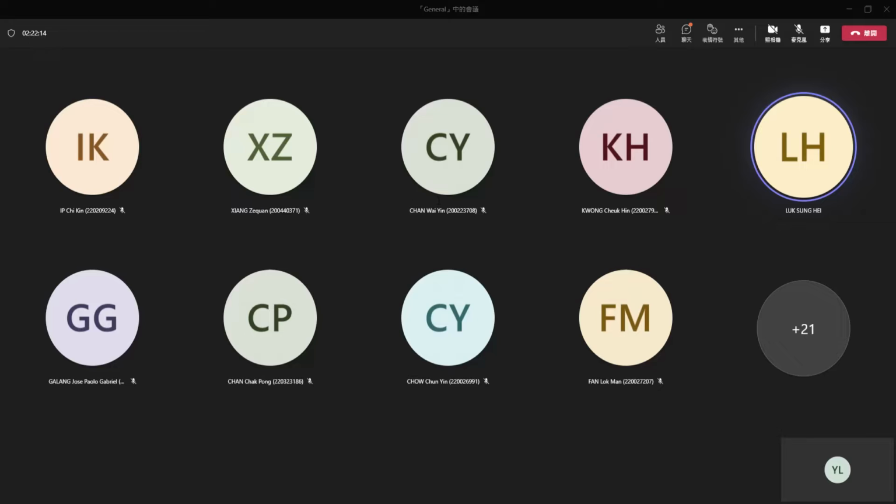I think with the Stiffness Method, maybe the most difficult thing is the mathematics, how to do matrix addition, multiplication, matrix inverse. In terms of the structural concept, I think it's not that difficult. You just need to remember some sign conventions, what is positive, what is negative, and you also need to know how to assign code numbers, how to assign degrees of freedom. I think these are the only new things in the Stiffness Method. The other thing is just related to how to solve the matrix equations.